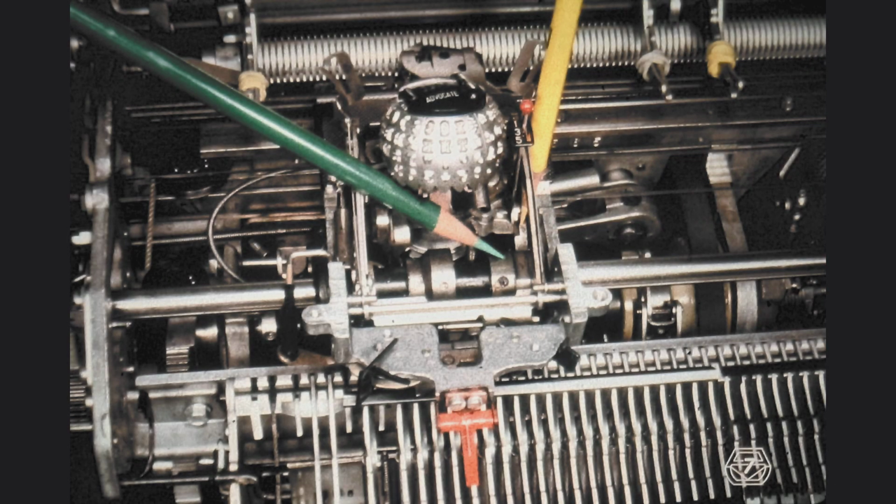Without the ribbon support plate in the way, it is easy to see the print cam at the green pencil with its two lobes. The print cam follower is indicated by the yellow pencil. It reaches under the print cam and is mounted onto the right side of the carrier. It pivots on a stud located approximately under the point indicated by the yellow pencil. Be sure to trace these parts on your machine.